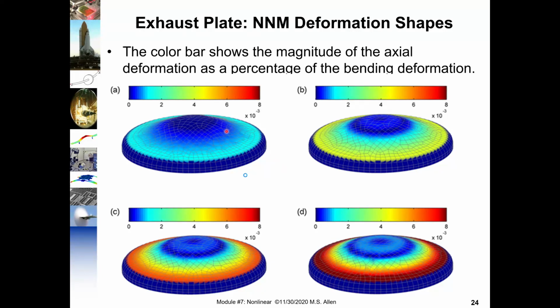Here are the deformation shapes for this plate. And one thing that was interesting here is that at high amplitude, with the large vibration, you get a redistribution of stress that can actually change the point where the peak stress occurs. So that can also be important. All right, but you saw the 2 key phenomena, and you saw that these scale to all kinds of structures: beams, plates, and almost anything you can imagine. You could see these same kinds of phenomena, and you could quantify them by thinking about nonlinear modes of vibration.